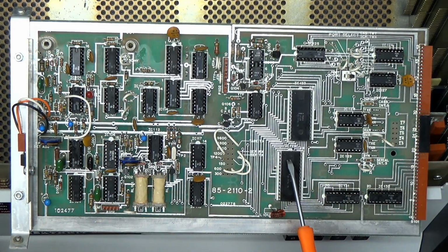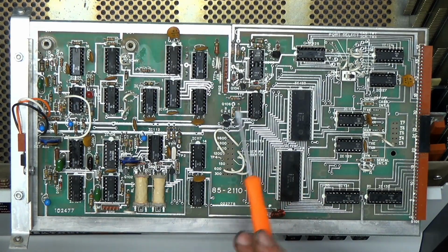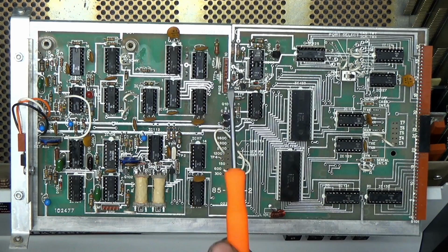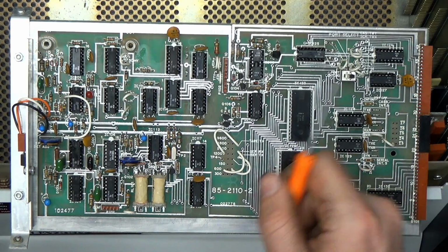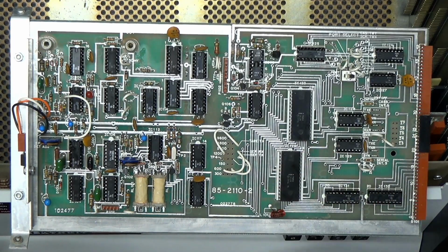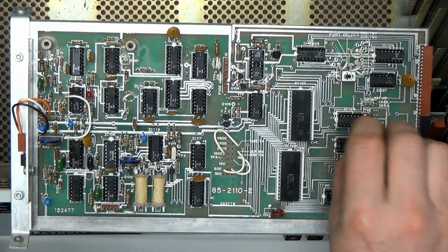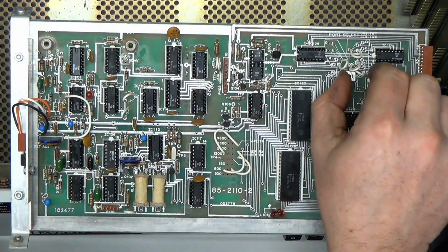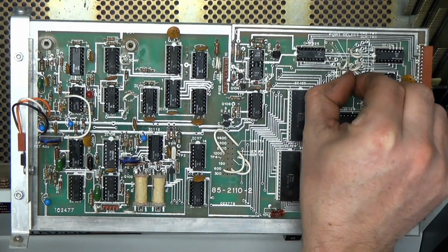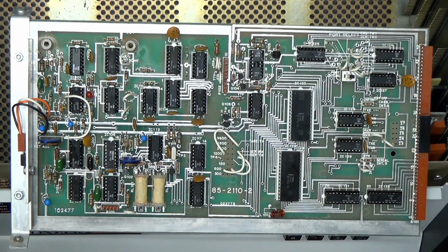We can probably bend those pins up and put a MAX3232 on a piece of proto board somewhere with a pin header on it, and then make a cable that goes from pin headers to a DB9 connector that we can mount in the back of the machine. And then we can just plug a null modem cable into it and rock like usual. And it's got a switch here to swap the terminal port and the cassette tape interface, which I assume was meant to be used with ASR33 teletypes that had paper tape punches built into them.